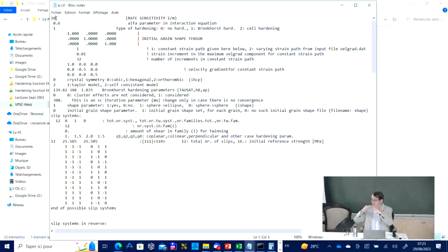It becomes so sharp, and we are always at the edge. The process cannot work. In reality, the yield surface is not so sharp. It's very much rounded, and this value 10 also makes sure that the yield surface will be rounded. So 10 is a good value.